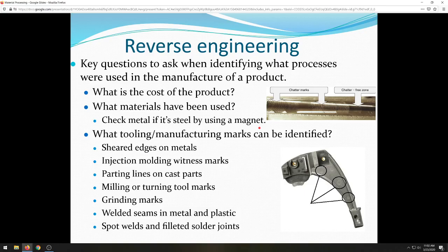Stainless steel, which is what a lot of common kitchen knives are made out of, does not hold an edge very well, but it's stainless and won't rust. Counter to that, a really high-end knife is going to rust because it's made of more on the end of regular steel, but it holds an edge really well. So a lot of manufacturers try to find this balance between the stainless properties of stainless steel and the edge holding qualities of regular steel, like a tool steel.